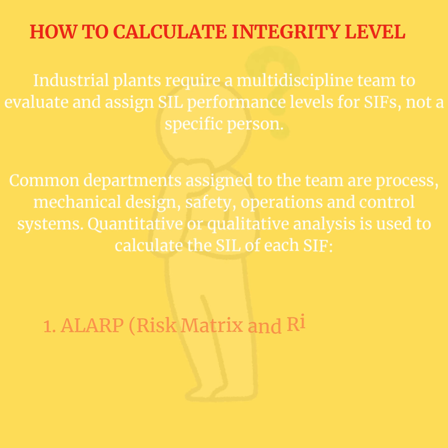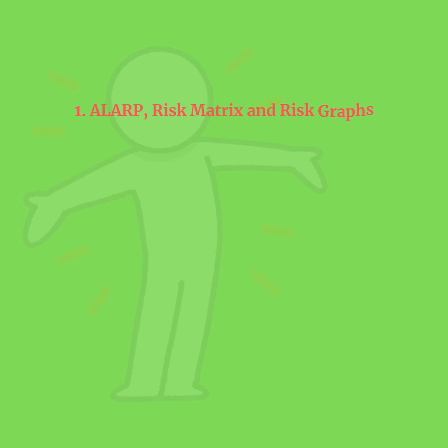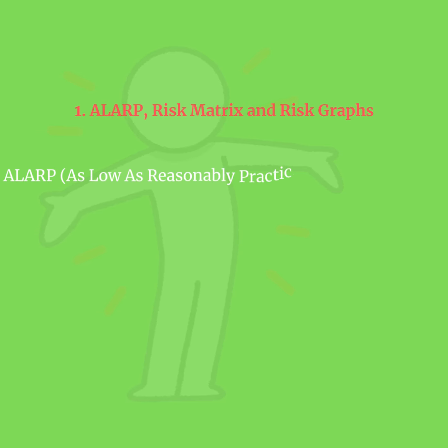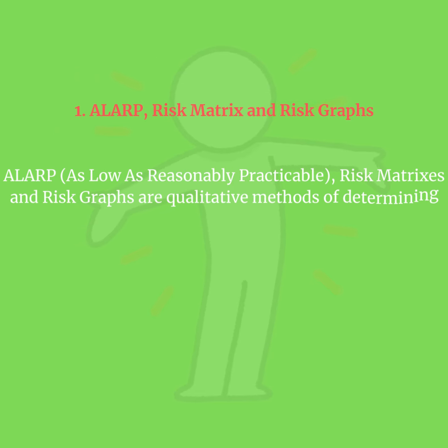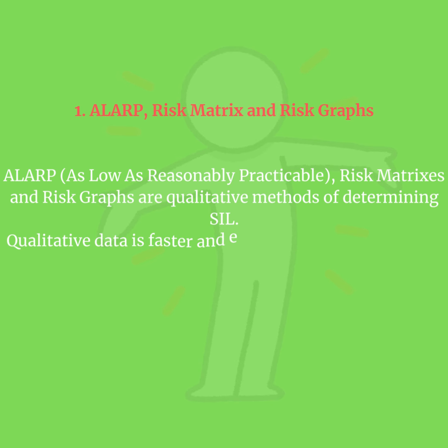1. ALARP, risk matrix and risk graphs. 2. LOPA, layer of protection analysis. 1. ALARP, risk matrix and risk graphs. ALARP, as low as reasonably practicable, risk matrices, and risk graphs are qualitative methods of determining SIL.